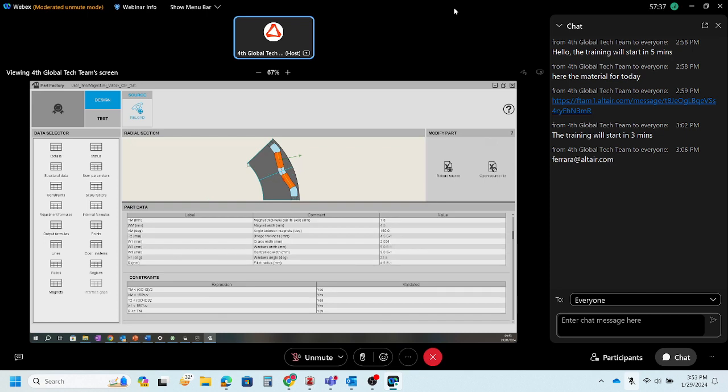Please pay attention each time that you use a new part, because each part contains some constraints, and we need to respect these constraints. Along the design, FluxMotor will help you to know these constraints, but it's quite powerful to check them before, because you are able to understand if there is some limitation with respect to the design that you want to reach.